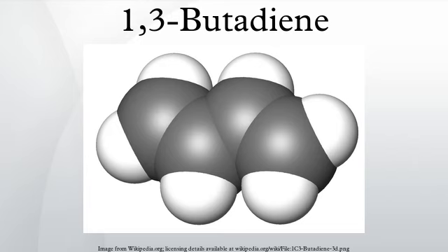The Louisville plant initially created butadiene from acetylene generated by an associated calcium carbide plant. The process remains in use today in China and India. From butanes, 1,3-butadiene can also be produced by catalytic dehydrogenation of normal butanes. This method was also used by the United States synthetic rubber program during World War II.